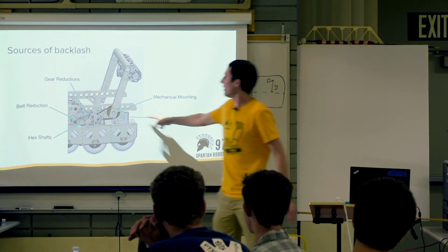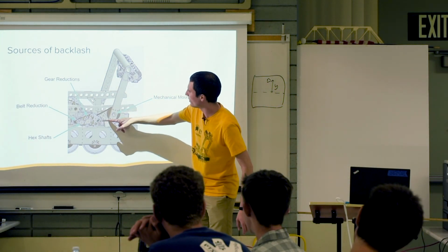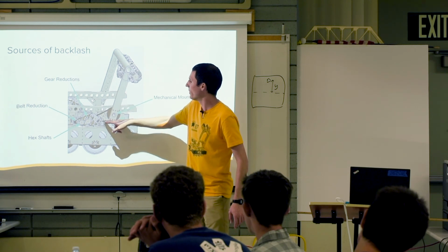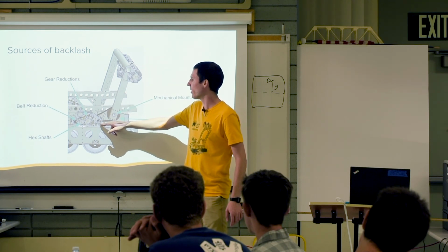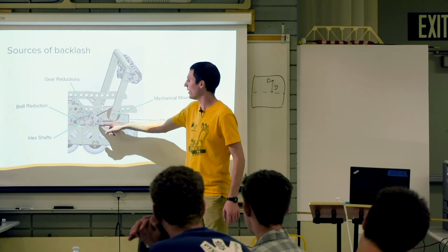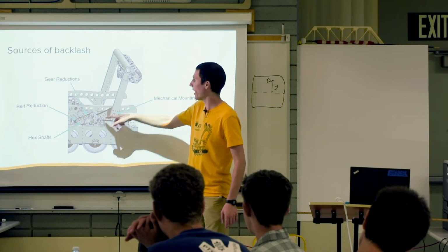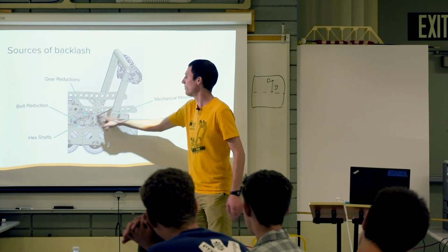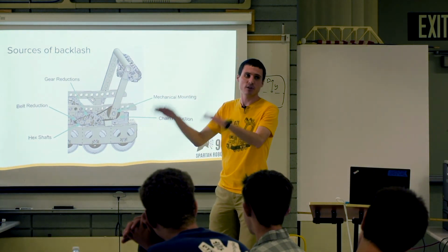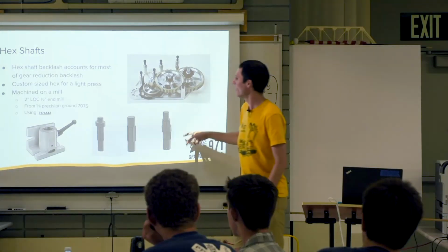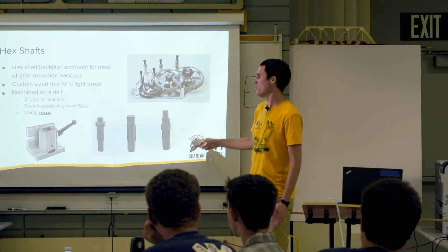If you look at this guy here, it's kind of hard to see because we didn't model it this way, but we have a midspan tensioner on this one. There's a sprocket here that's in a slot. We have a pusher bolt that pulls it up this way. And if you look at this system here, we expect the main force to be working against gravity.